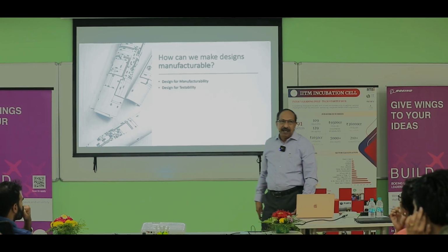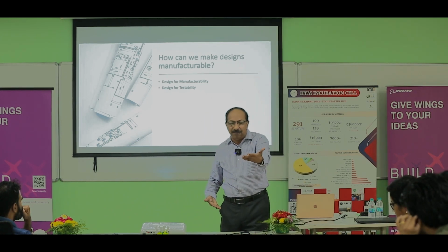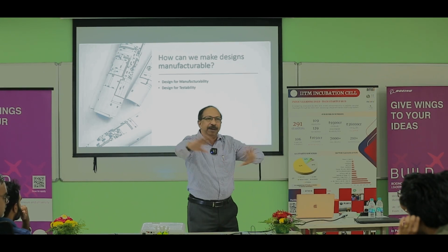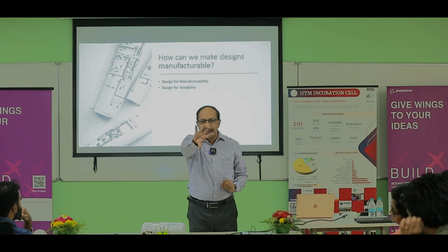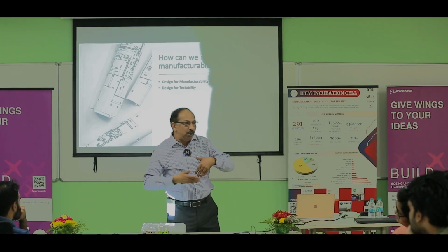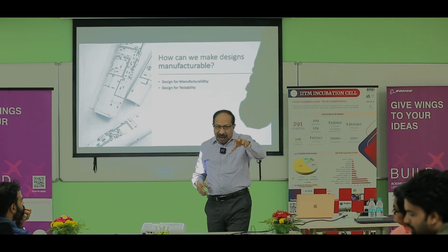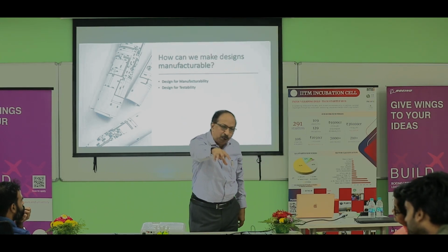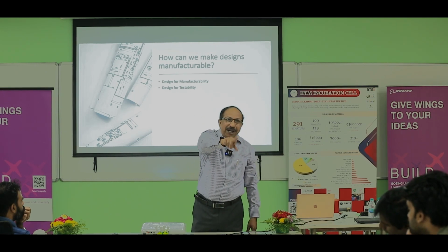Design for testability. Testability is another thing. You are developing a product, you are manufacturing a product, for example. It starts from one stage, and when it reaches the other end of the table, the product is completed. If you blindly send it through all these stages, at the end it can happen that the product is not working, so you lost everything. So for that purpose, when you do the manufacturing, at various stages there are test jigs, so that you can test that up to here it is working, up to here it is working. If it is not working, do a rework and then take it forward.